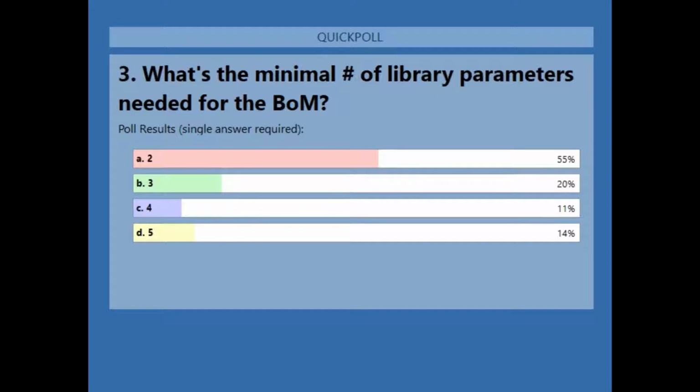And so if someone said, well, what about the description? Yes, I would totally want the description in there. To me, the description is the holy grail of all parameters. It's not one that should be taken lightly. As a matter of fact, Altium treats it as a system level parameter. It's that important, as opposed to a user parameter. So in a typical part, you have to have a description, or at least Altium gives you that text automatically to say, hey, fill this in.